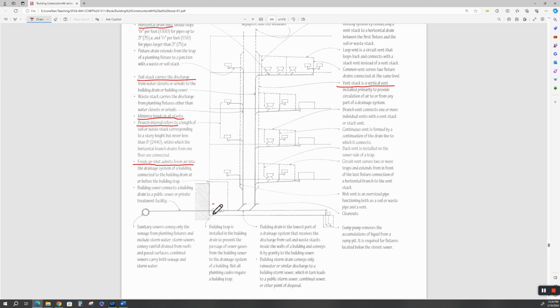All right, this is a clean out, CO. I would not skimp on the number of clean outs. The worst thing you can do is have a sanitary sewer system without enough clean outs to get in here and rod this stuff out. Either jet it out. You also want to run cameras if you have a problem, because sometimes as ground settles, remember settlement, these pipes will settle. As the ground either subsides or consolidates because they didn't backfill it properly, you'll have a belly in this pipe, which means water that sort of maintains and stays in here and starts to decompose, and solids will drop out, and then your 8-inch line no longer is 8 inches.